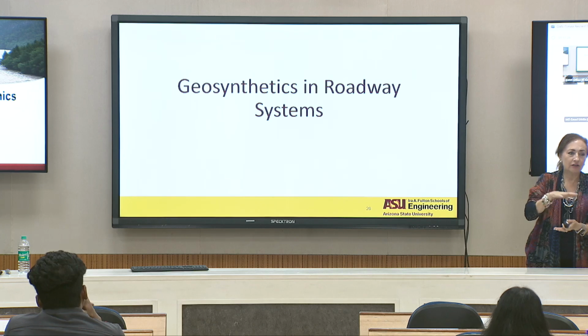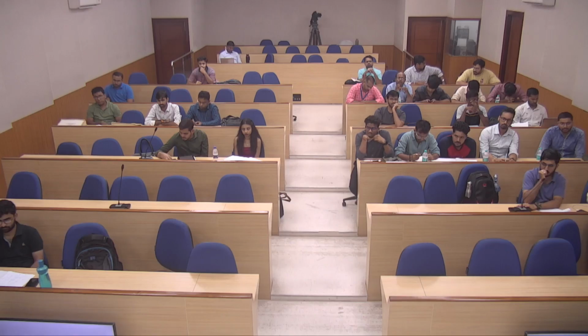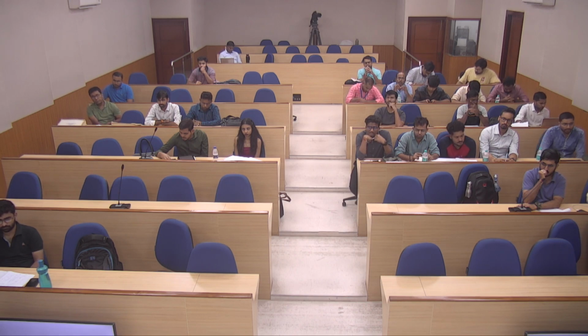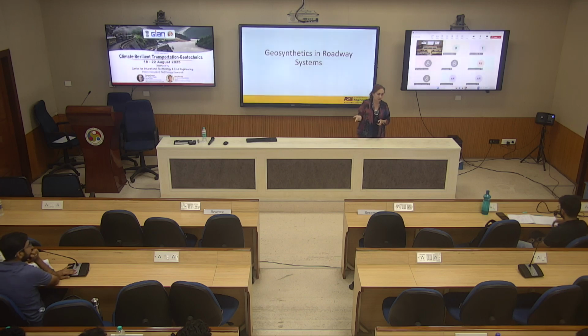Basically you prepare several samples, subject them to different cycles, and measure how much reduction in the unconfined compressive strength there is after a certain number of cycles. That's exactly what I think they do, but I didn't bring the methodology. Does that answer your question? I think it's the unconfined compressive strength, yeah.